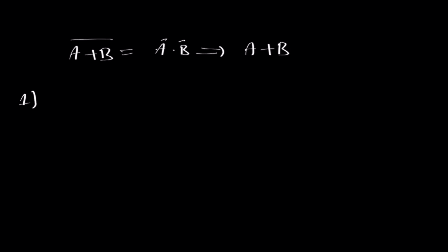Okay, so let's apply these 4 steps to De Morgan's theorem, which is A or B long over bar, that is equal to A short bar ANDed with B short bar. So let's see how we get from left to right. Following De Morgan's theorem, step 1 was anything that you see AND will become OR. So we will write this one down as A or B long bar equal to Y.